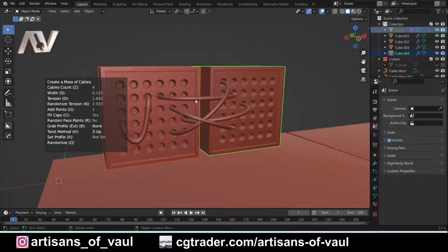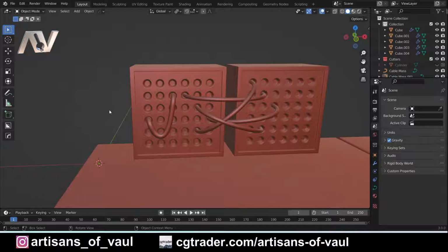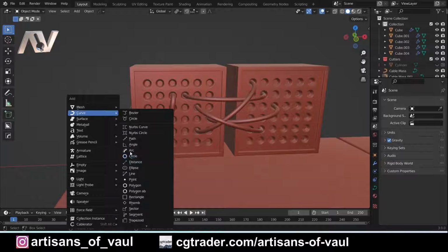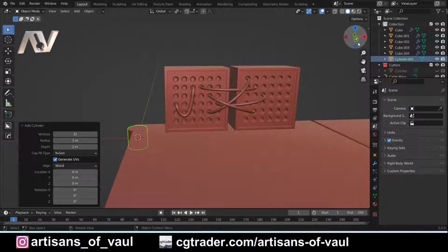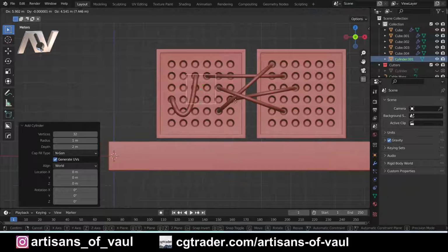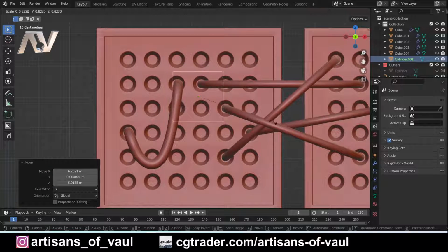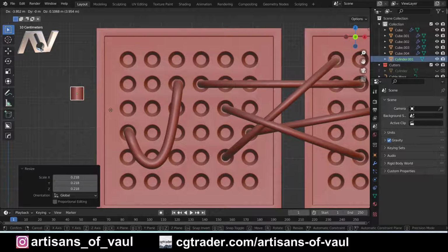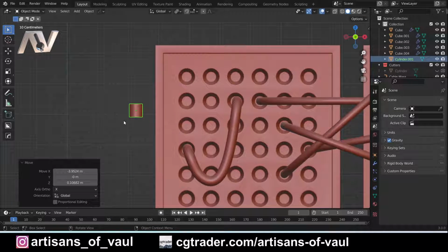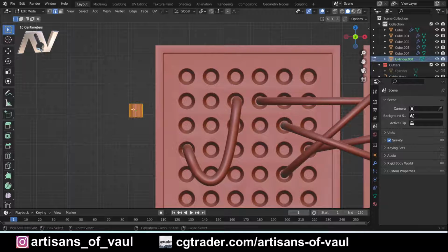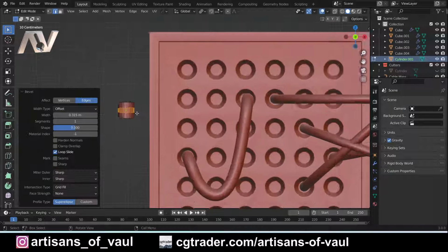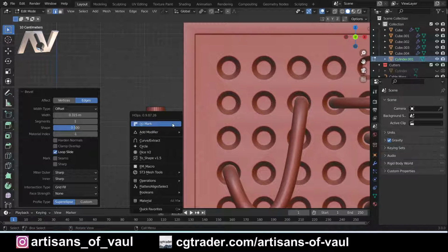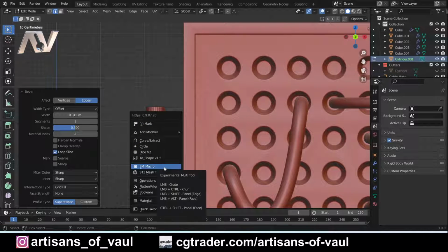So let's click off and let's make a connector. So we need a cylinder. Let's get that to being about the right size. So S, something like that. Move that over to the side. Then, just so it's interesting, edge mode, Shift R, done. Shift B, make it a bit bigger there. And then Q, because we've got hard ops. If you don't, you'll have to do this manually.